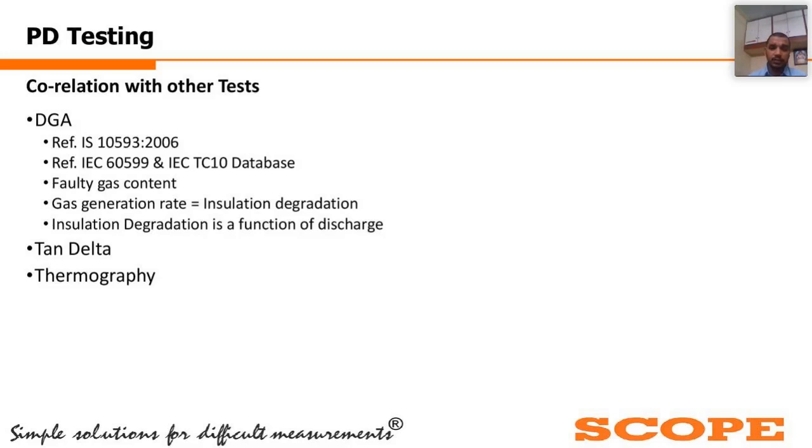Okay, I think partial discharge is happening, and we must try to pinpoint it, or we must try to find out why exactly that is happening. Because pinpointing is not possible with DGA, or with the tan delta, they are not possible. So they go with partial discharges.